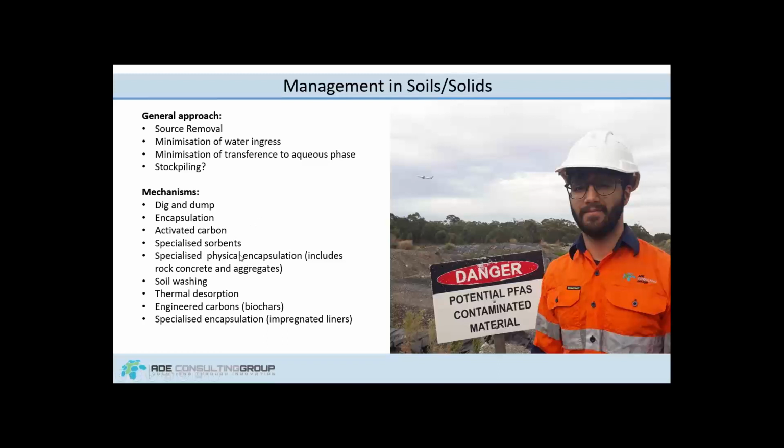Specialized sorbents include formulations or mixtures which are designed specifically for PFAS contamination sorption, such as Rembind and other competitors to that brand. So there's Fluorosorb. There's a number of them out there, and they have been specifically targeted at managing PFAS. Specialized physical encapsulation can include solidification, which is the use of cementitious products to capture PFAS, which I'll touch on in a minute. Soil washing is one that's been explored and has had some success.